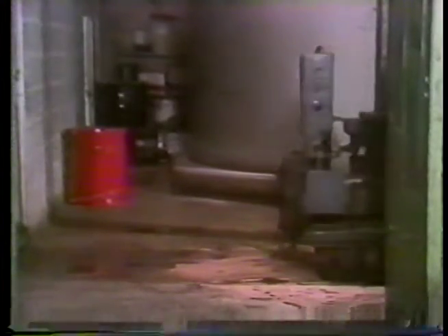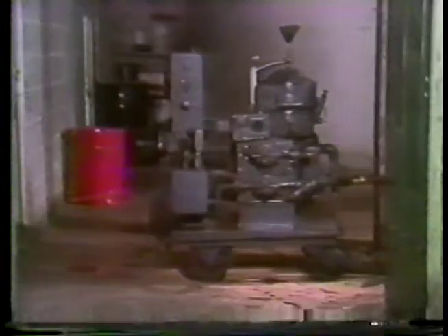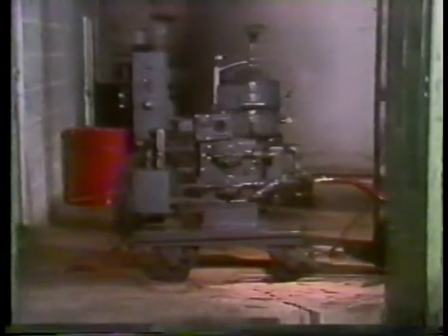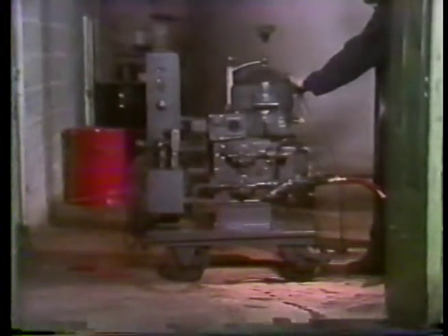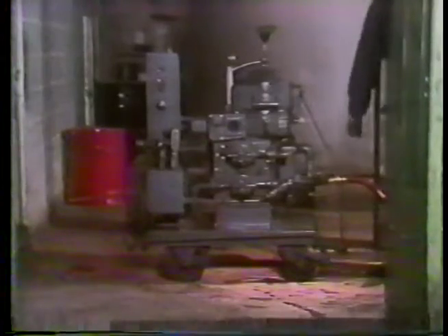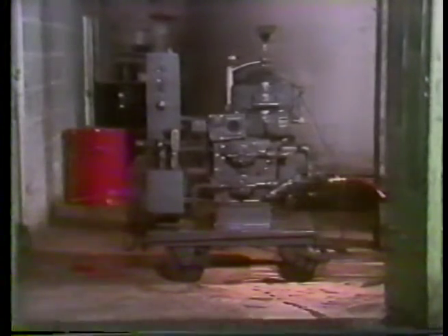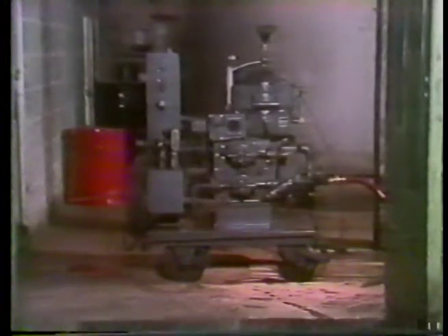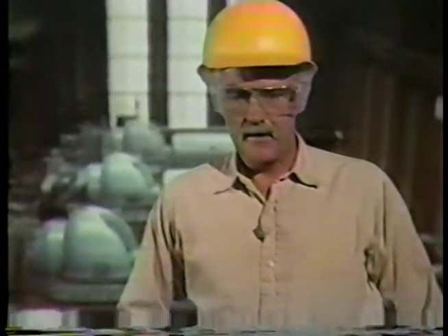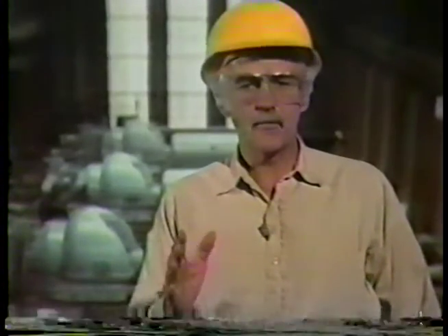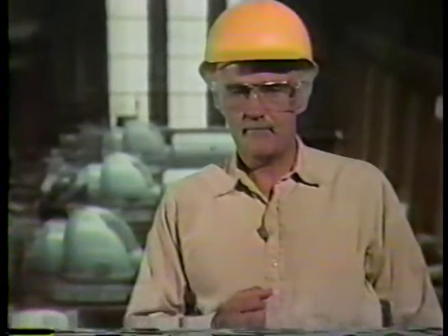The oil can also be spun in a centrifuge, where the impurities can be separated from the oil by centrifugal force. This particular centrifuge is portable. It can be used for a variety of lubricating systems. No matter how the oil is purified, by filter or centrifuge, the purification process can be done continuously during normal turbine operation, or periodically during turbine shutdowns.